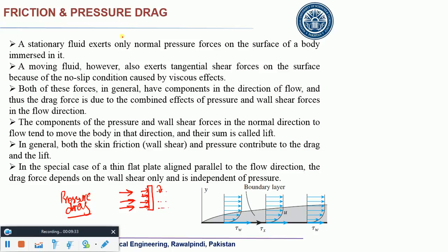There are 2 components of the drag. Just to continue my discussion, one component is based upon pressure and the other component is based upon, you know that, we have been talking about that stuff. Similarly, there are 2 components of lift, one due to pressure and one due to friction. Okay, so this force is generated by shear stress and this force is generated by pressure difference. Remember that. Okay, just go back, check your fluid dynamics notes, and you would have that discussion.